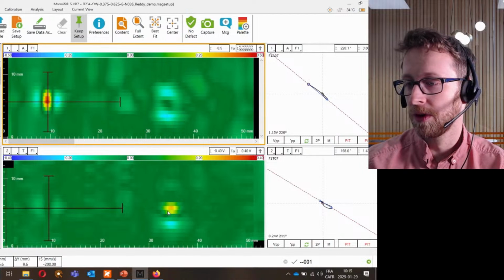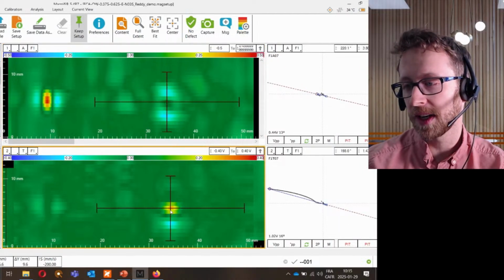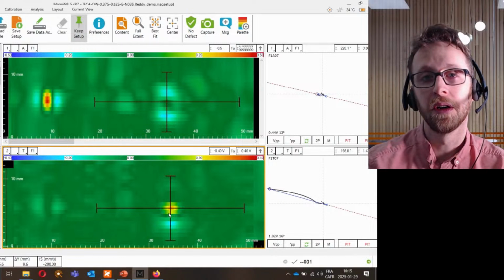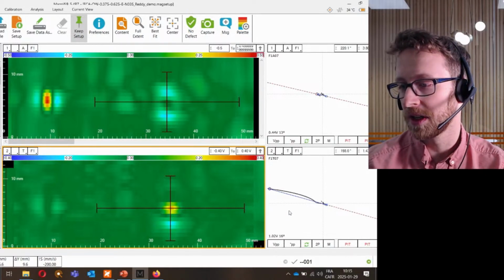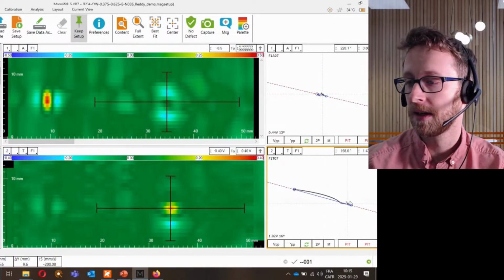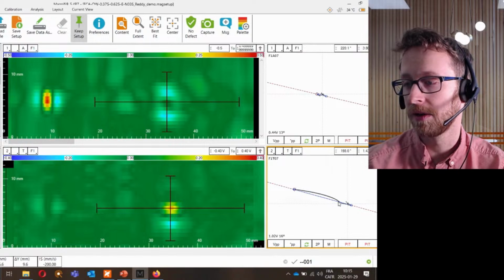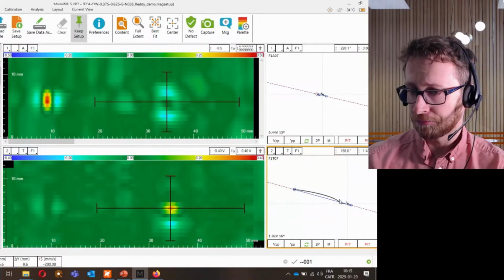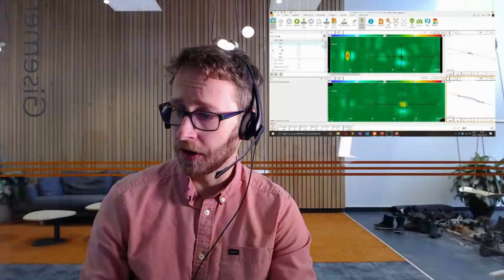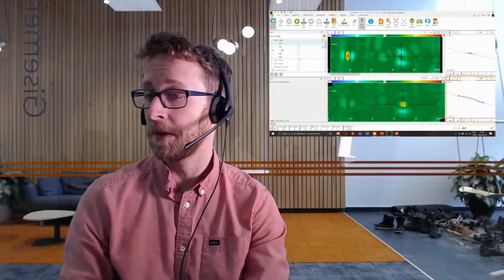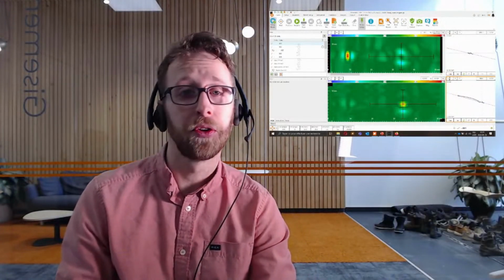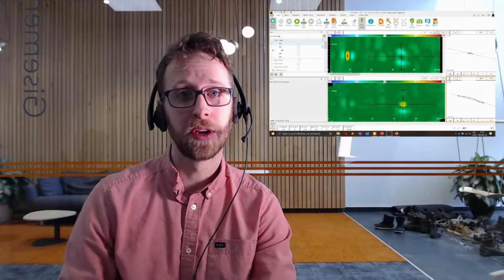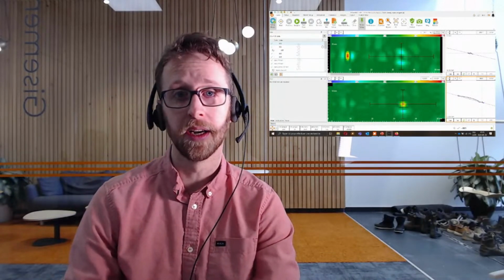And as I move to the transverse defect, it doesn't appear in the actual, but only shows up here on the transverse C-scan. And you can see on the impedance plane that beautiful crack right here. And depending on the material that you're using, depending on the frequency also that you're using, you might get different results. But this is to give you an idea of the detection capability of the probe itself.